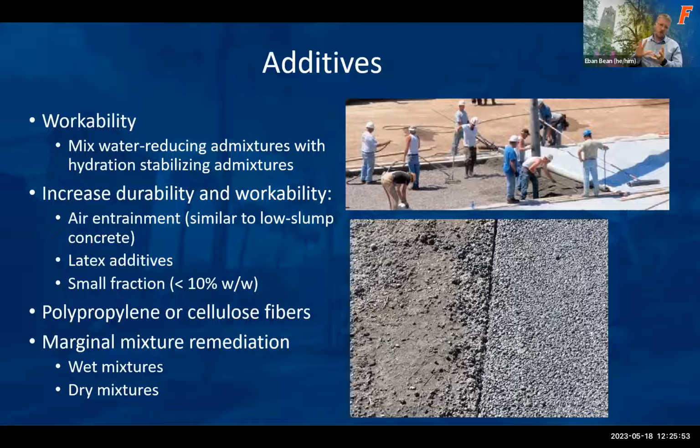And then there are some remediation options for when we have too wet a mixture or too dry of a mixture. One of the things that I think I'll touch on a little bit more is that whenever it's being cured in place, the cure time is very critical to having a successful installation. And that's why it's really important to have someone with experience to install this. If the mix is too dry or it dries and cures too quickly, it becomes brittle. And essentially you can have what we have in the bottom image on the left, where it really breaks down, crumbles, and the added traffic and raveling of those particles generates sediment and it clogs itself.